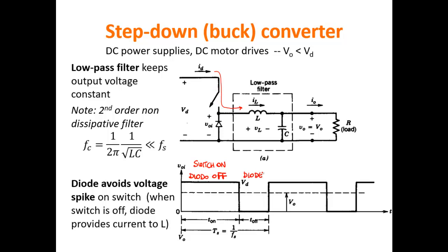what happens is that no more current is coming from the input to the inductor, but the inductor needs to have current. I mean, it does not have a will. That is simply the way it works when you have a reduction of the current in the inductor, the voltage at the ends of the inductor changes. And in which way does it change? It changes in order to counteract the decrease of current. And so this node goes down in order to call for more current.